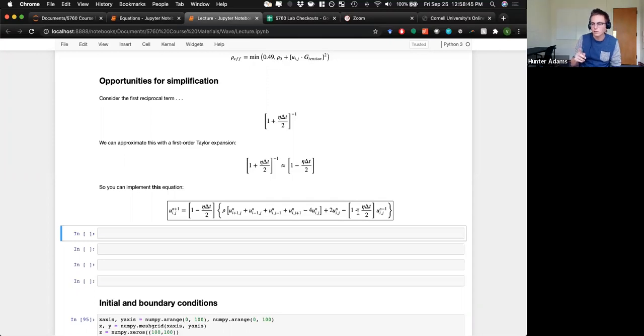And we'll take a look a little bit later at the hardware resources that are available on this chip. It turns out that you have 174 18 by 18 hardware multipliers available. So if you think about that, 174 multipliers, if you require 2 multipliers per node, you can start to do the math about how many nodes you can parallelize in a single time at a single update before you run out of multipliers. We'll think more carefully about this in a moment.